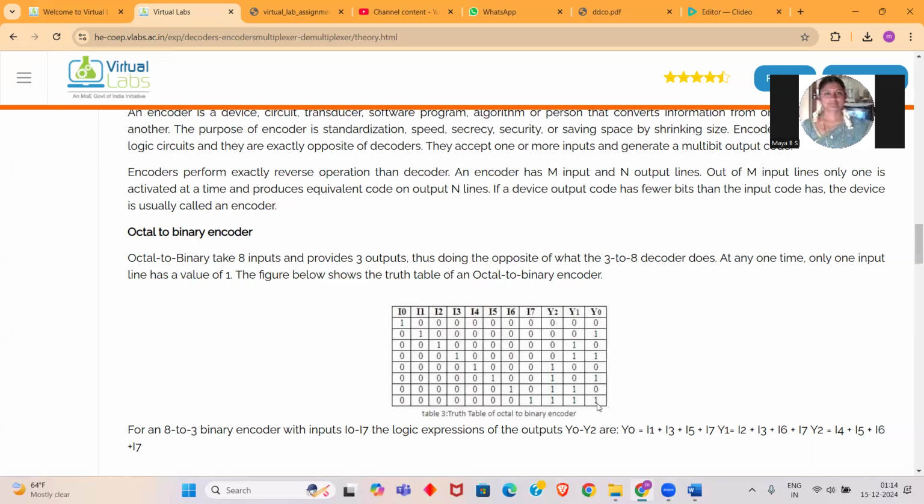See, we need to do the circuit diagram in class. You need to take the value of Y2. You take the summation of the output line of Y2. So wherever a 1 is present in the truth table, you take the corresponding value. See now, this is my Y0. Wherever Y0 is 1, the corresponding inputs are I1, I3, I4, and I7. See, that is how Y0 is written.